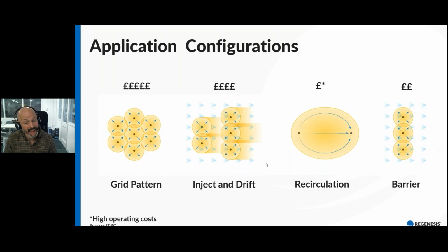And very occasionally, for example, in a deep bedrock setting or to avoid above or underground obstructions, we can use a recirculation method. That is, we would apply in one location and we would extract in another to draw the reagents across the formation. And again, we make these decisions in the context of the site evaluation.